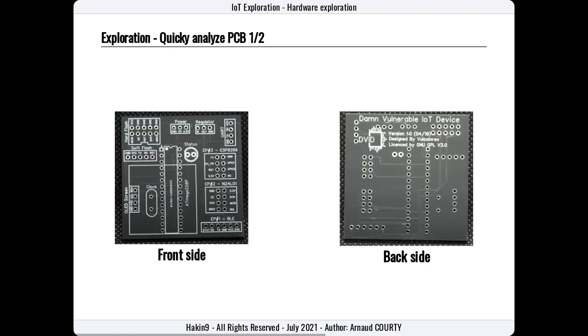From the provided picture of the device and after removal of the screen, we can see that the system on the chip is an Atmega 328P. This information is useful for looking for datasheets, download, and getting information about the standard UART communication port. At the bottom, there is also an extension port named BLE. It means that the board provides a Bluetooth connection.